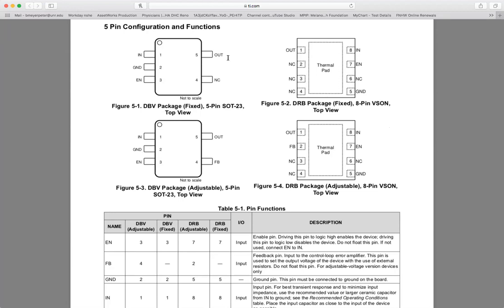But just how this works. So you have your voltage coming in. You have to have a ground so it works, because the voltage it uses to work has to be grounded so voltage flows to run it. Maybe for other reasons too. But you have this IN pin, and then you have this enable. If you have voltage running in enable, it's on. If you turn off the voltage, like if you just had a push button switch here that turned it off, it would turn off the output. So this is just a switch, on or off. And they've got it rigged so that it can turn on voltage or off.